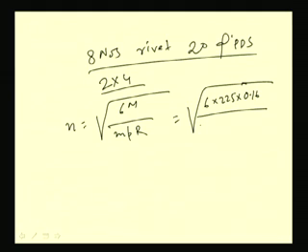So, let us assume that in 2 rows the rivet has been distributed, so n is 2, and let us assume the pitch at say 60 mm, that means 0.06 into R, R is 36.3 kilonewton. So, from this I can find out the number of rivet.